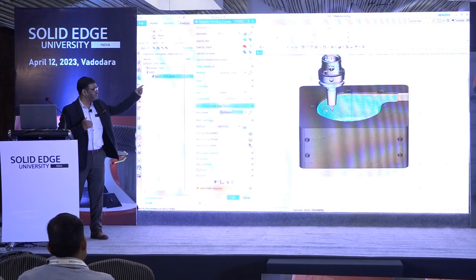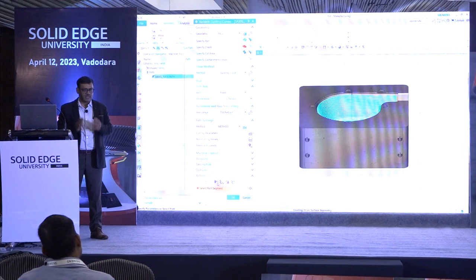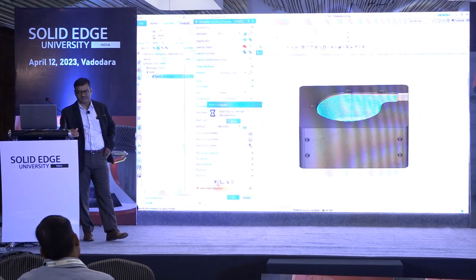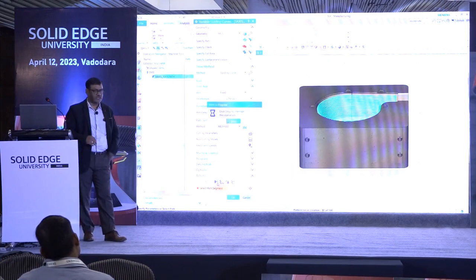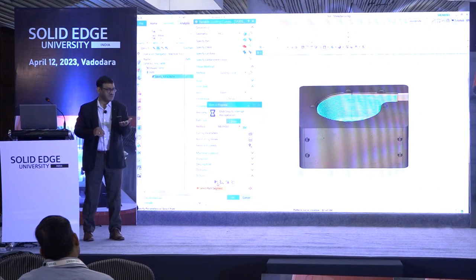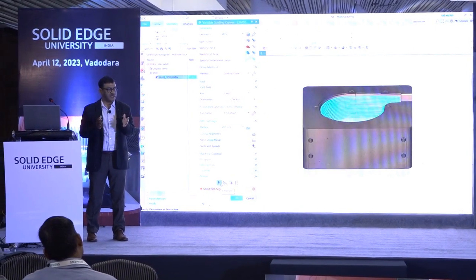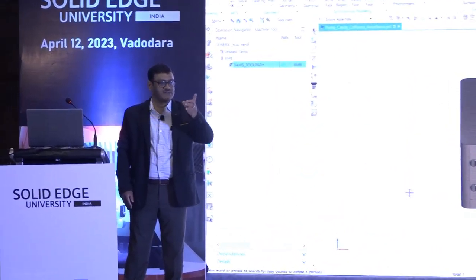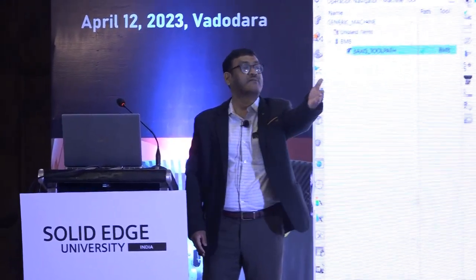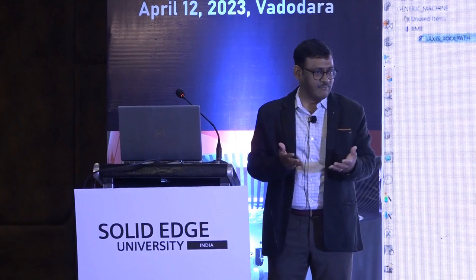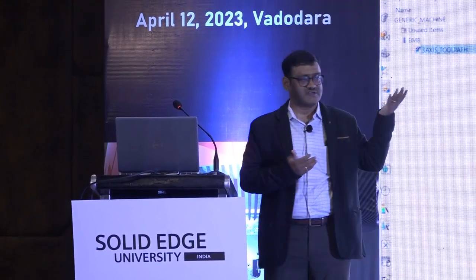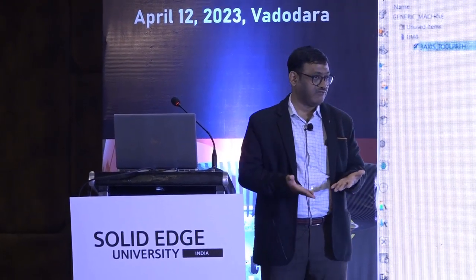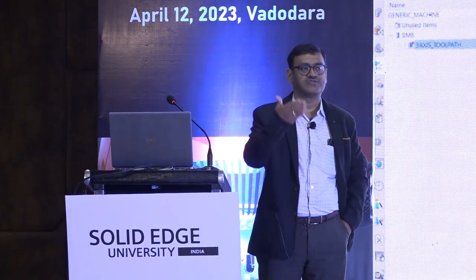This is where the software makes an inclusive product enhancement where we tilt a 3-axis toolpath to a 5-axis toolpath. You just say tilt by 15 degrees, and automatically the 3-axis toolpath is converted into 5-axis if you have a machine. I know there is a gap: if you don't have the machine, you cannot use this function. But if you have a machine which is capable of 5-axis, I want you to use it fully.